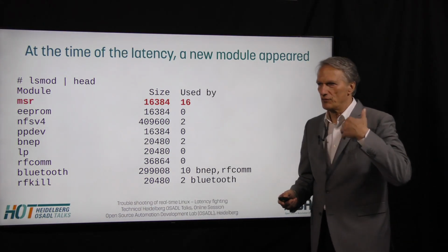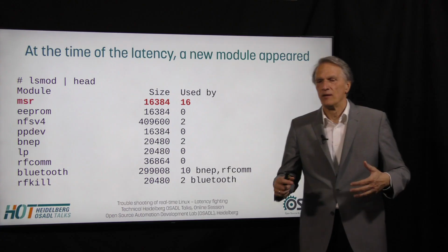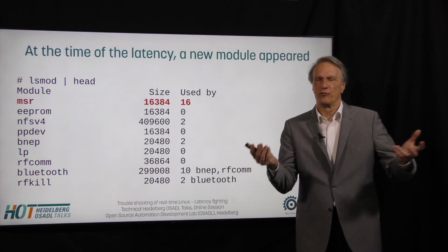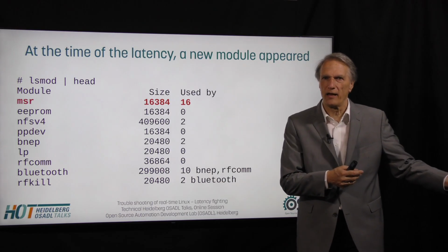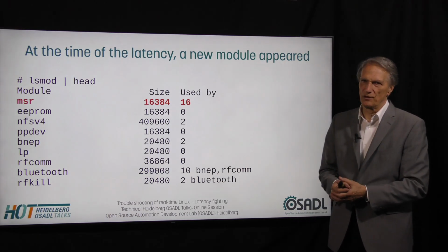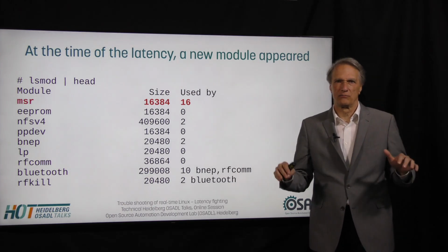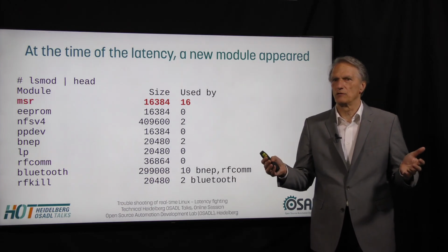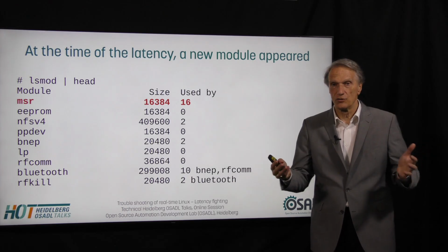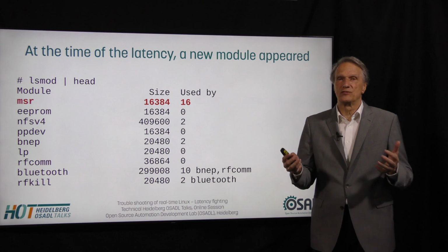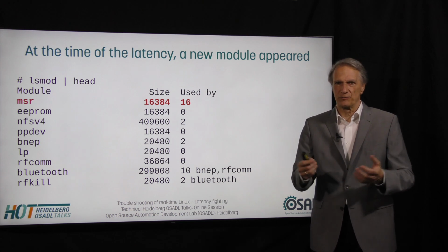So we can now reconstruct this latency. For some reason, the system became too hot. Maybe the performance requirement was too high, maybe the cooling was not good enough. In response, the kernel throttled the frequency, which is, well, good to know. Certainly we would have seen this, but this normally would not create such a big problem.